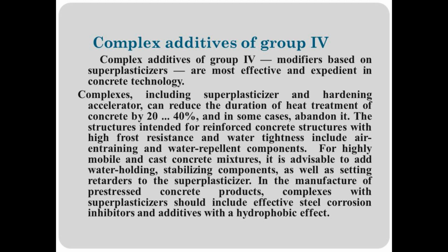Complexes, including superplasticizer and hardening accelerator, can reduce the duration of heat treatment of concrete by 20–40%, and in some cases, abandon it.